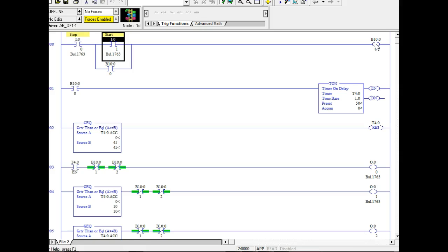Most of your current PLCs have a 24 volt power supply on the PLC, but that is not intended to run outputs. That's just intended to run the inputs, because they require almost no current. So that means your outputs usually require an external power supply.